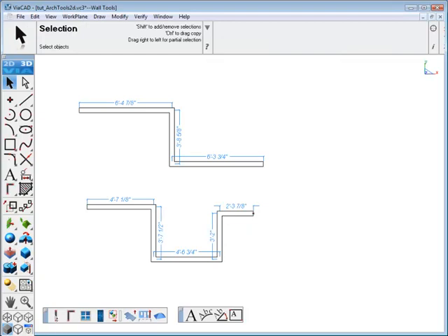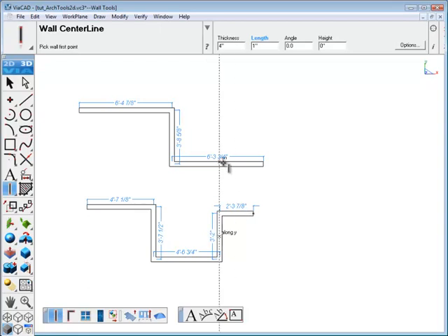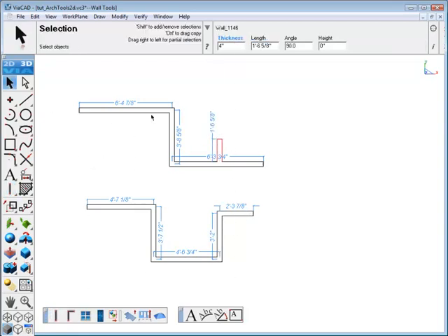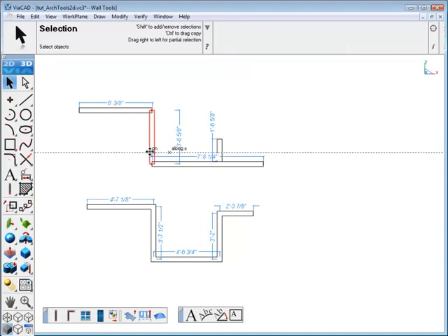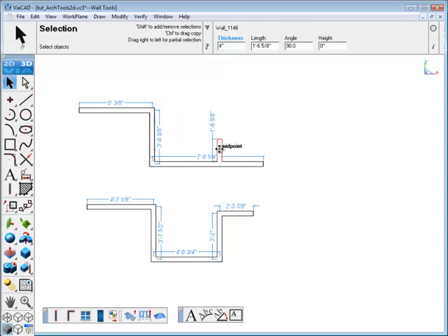We'll add another wall intersecting this horizontal wall. Notice that the intersection is cleaned up automatically. And the intersections are also automatically cleaned as you move the wall along the other. Moving it all the way to the end, you'll find that it even creates the corner properly.